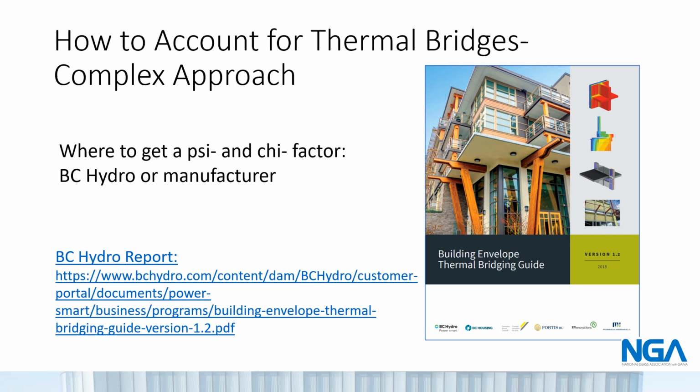Thermal modeling and testing presently do not typically include the perimeter joint or any thermal insulating materials that may be placed in them, although it is possible that they could be added to get a more accurate prognostication as to the thermal performance occurring or not at the perimeter of the fenestration. Based on how the general contractor divides the scope of work and which contractor is going to do what, and the sequencing of the work around these perimeter conditions, the relevant subcontractor's submitted shop drawings should provide the details needed to conduct an energy model of the system.